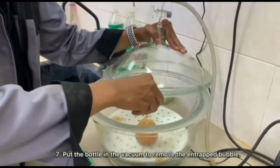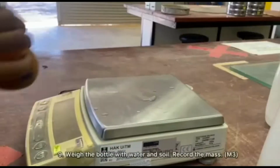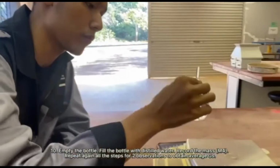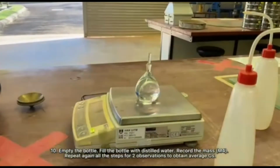And then put the bottle into the vacuum to remove the trapped bubbles. After that, pour some distilled water until it is full without any trapped bubbles. And then weigh the bottle with water and soil and record the mass. After that, empty the bottle, fill the bottle with distilled water and record the mass, which is M4. Repeat all the steps for 2 observations to obtain the average, which is Gs.